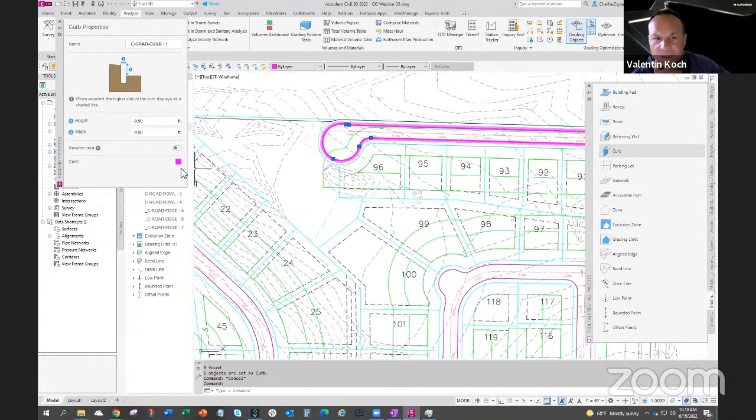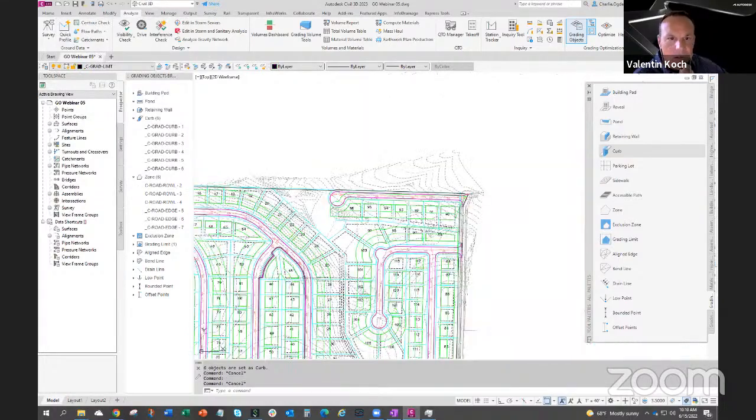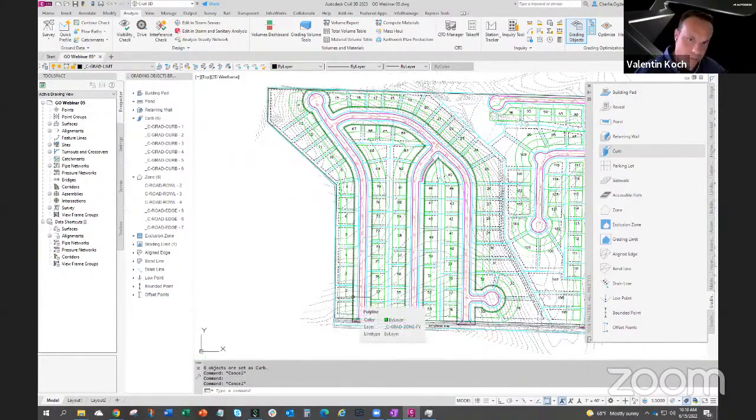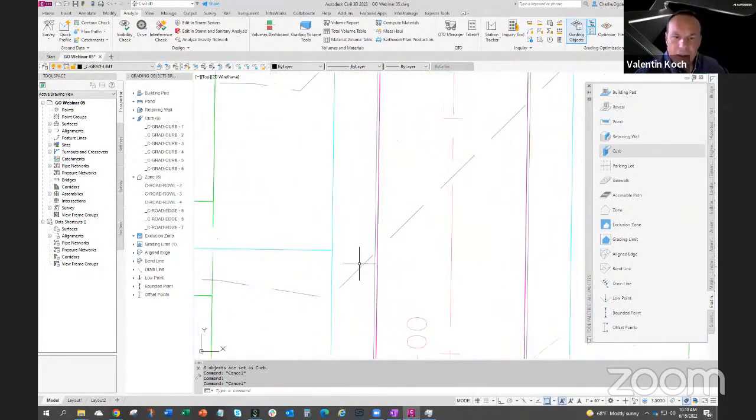And now the curbs, they also have a different functionality in this case than just making it look nice. Curbs are mainly under the hood. They're just offset points that go along the road, and you create a little zone that is your curb wall with infinite max load. Then there are offset points from the top of the curb down to the bottom of the curb. And these offset points happen at quite small intervals.